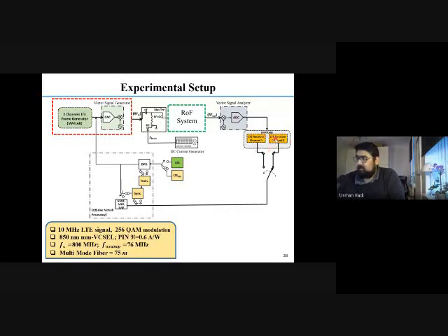With this signal analyzer, we had a MATLAB-based setup. Now we have a signal analyzer which already has all these types of communication systems, but at that time we implemented the MATLAB-based LTE receiver. So you have channel 1, you have channel 2. For instance, you are using channel 2. You receive the channel 2 output, and then you bring it to your offline MATLAB processing block, where you measure the minimum mean square error, or ACPR, that we discussed, the adjacent channel leakage ratio, or error vector magnitude.